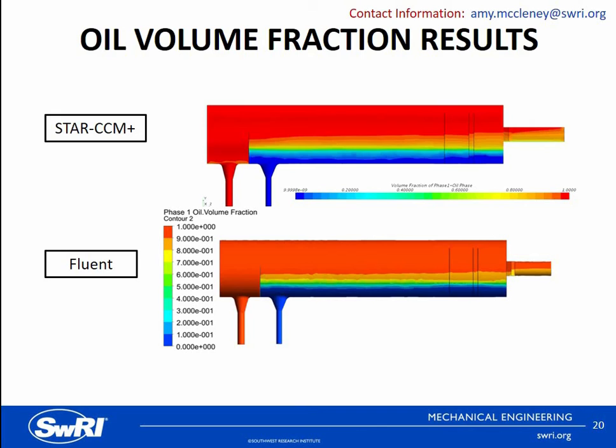Once the fluid exits the inlet device, the dispersion layers of the oil and water can be seen separating into the pure bulk fluid phases, where the concentration profiles remain relatively constant until reaching the solid weir plate. A thin fluid mixture layer is observed, and it maintains a relatively constant thickness past the last perforated plate.